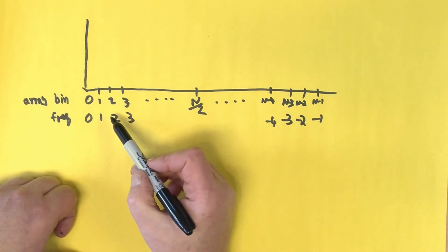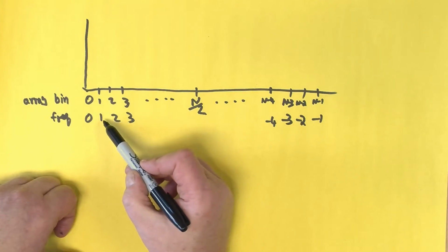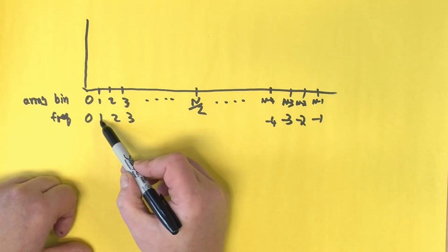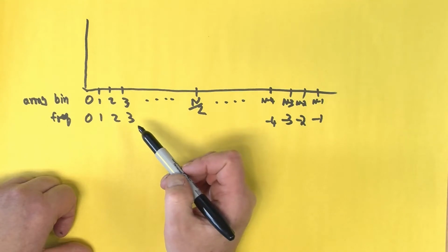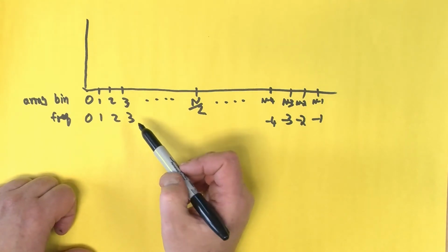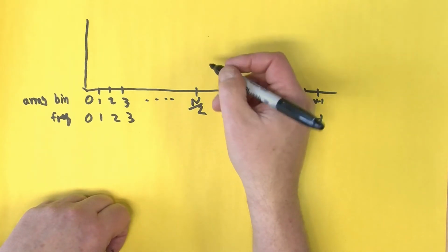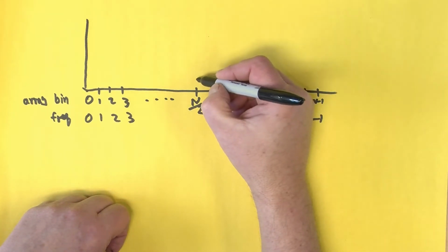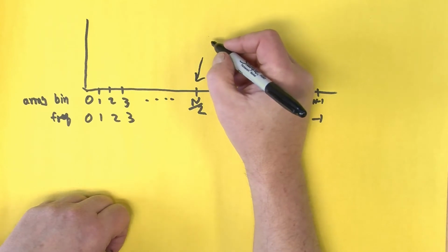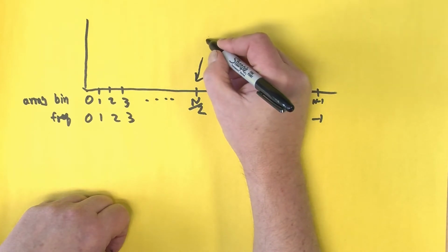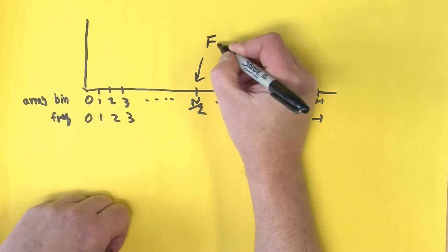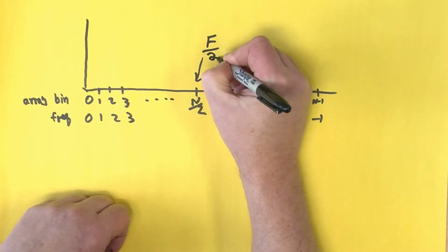And again, what we really would like to do is know what each of these bins corresponds to in terms of a real frequency. And we can do that quite easily because we know this middle bin, as we said before, corresponds to the original sampling frequency over 2.